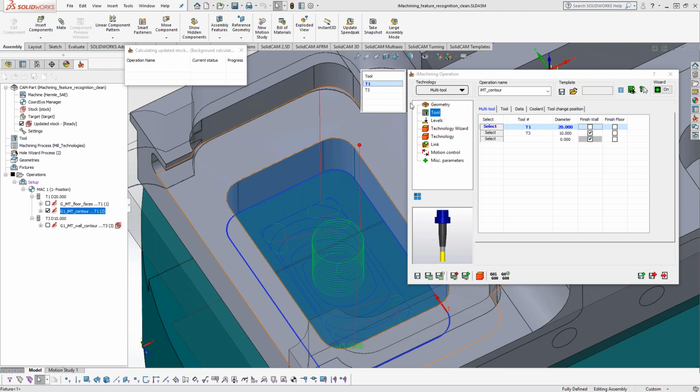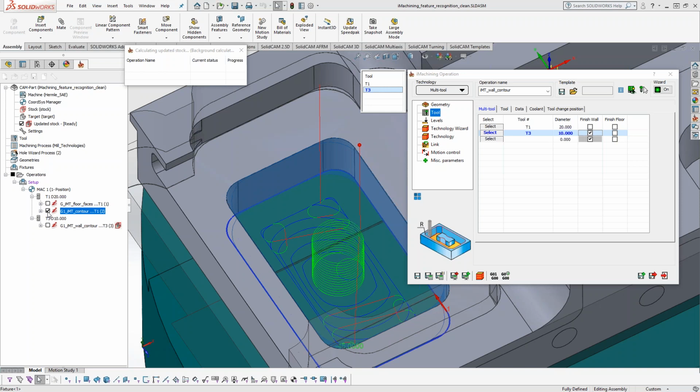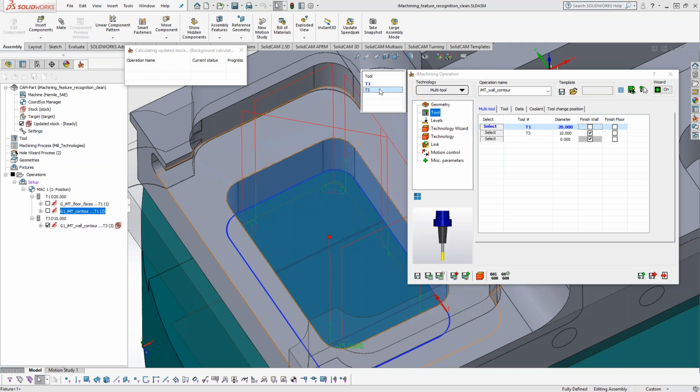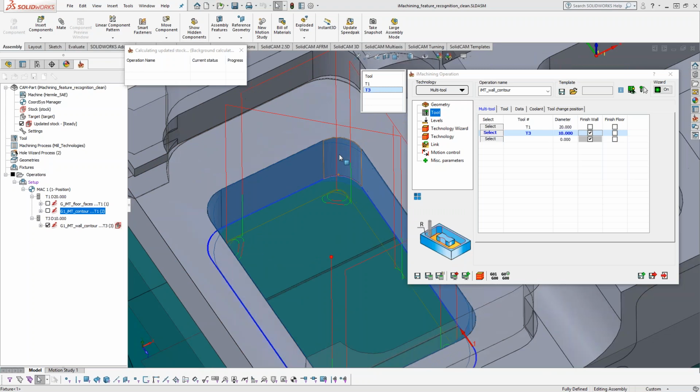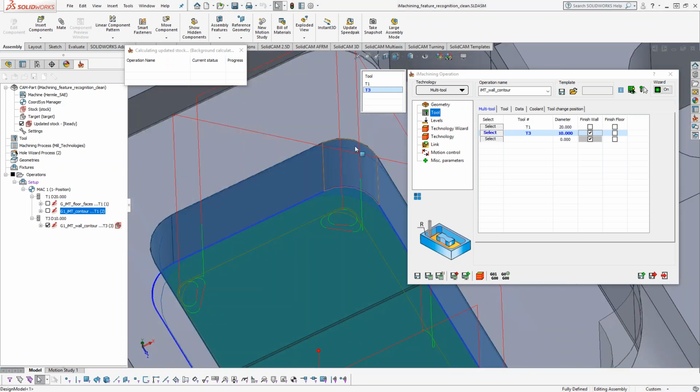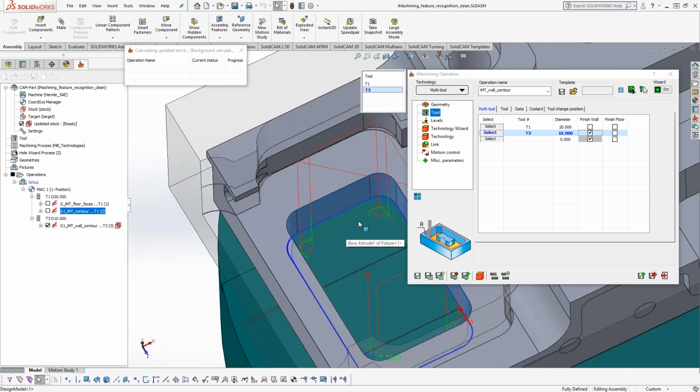When you do the preview and you click between these, you can also see, pretty neat, the 3D preview update based on what tool is active in the multi-tool. So when we're highlighted on the first tool, the preview shows the entire pocket, right? Because we haven't machined anything with it. When you click on the second tool, which is doing rest machining and finishing the wall, you can see, hopefully it comes through the GoToMeeting, some of the colors might get washed out a little bit, that we just have material in the corner, and then there's some material on the wall.